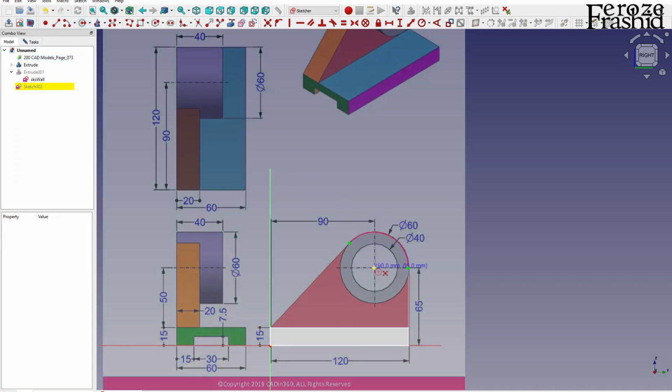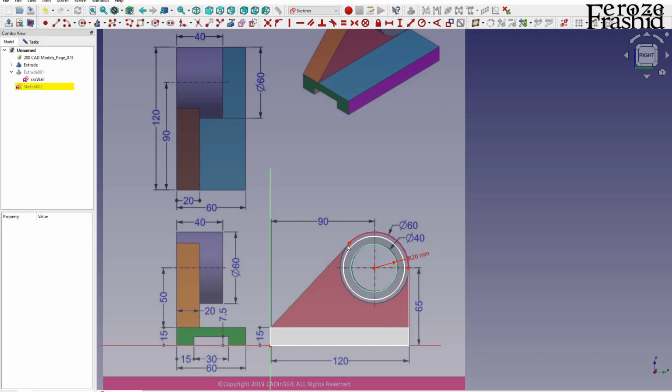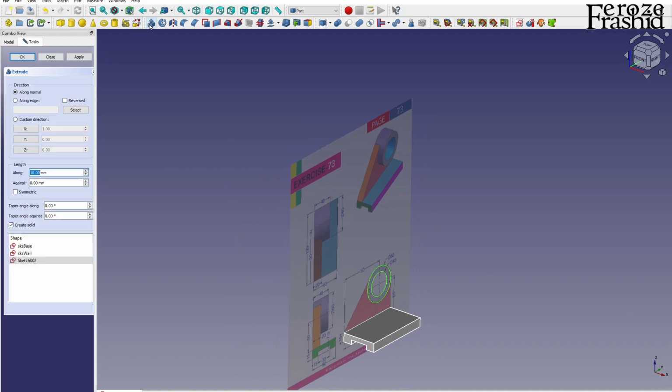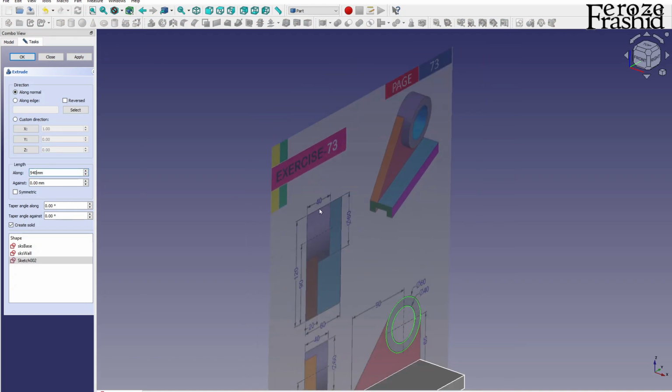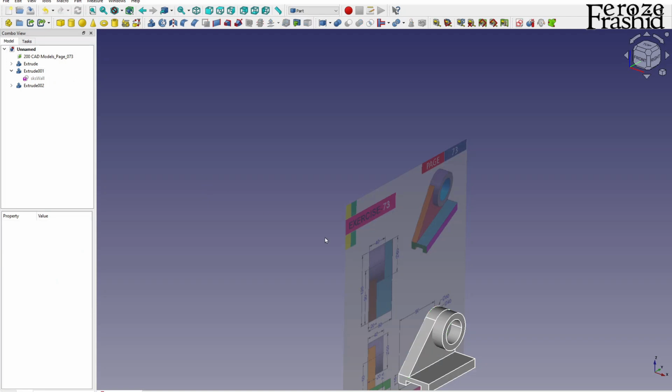I could do the same thing with a primitive, but let's try this option. Okay, this is diameter 40, which means radius 20. That constrains our sketch. This is the hole. Pull that forward for 40. Let's bring back our wall, and there it is.